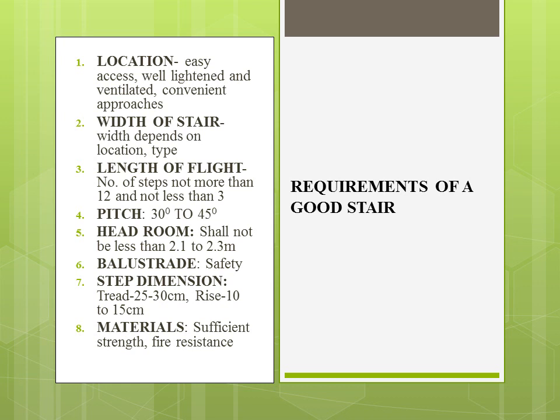Headroom shall not be less than 2.1 to 2.3 meters, and the balustrade should be provided in order to ensure safety. Step dimension: tread should be between 25 to 30 cm and rise 10 to 15 cm. Materials used for the construction of step should have sufficient strength and it should be fire resistant.